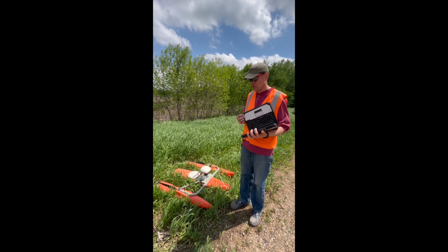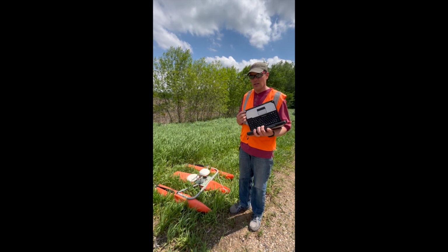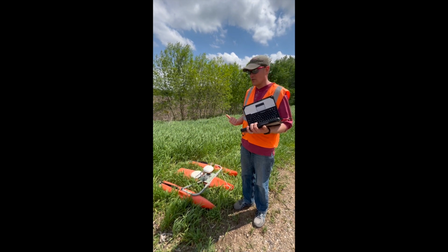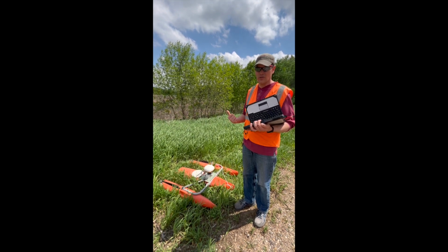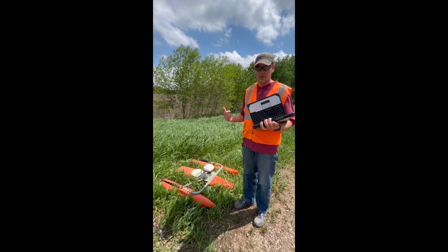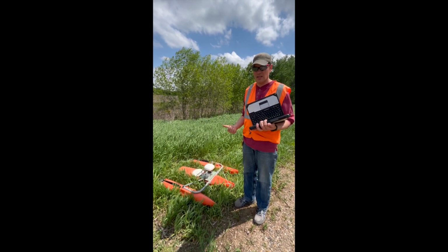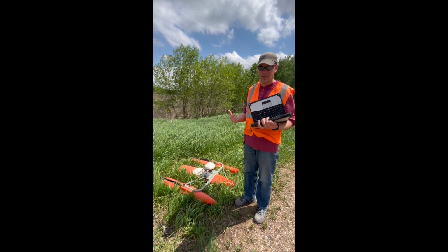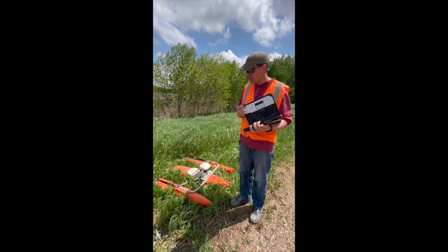Now we're here with the River Ray. We're gonna set this thing up to take a discharge. Sometimes you want to use the Ray for higher flow events, or if the stream is too dirty, the StreamPro can't see through the grit and grime, so then we have to take the Ray. If we have a really high discharge that we're past 5 feet per second, then we have to use the Ray. If we're under those readings, which right now all the Big Sioux is pretty much at that point, the Ray is still something that might be available for different conditions.